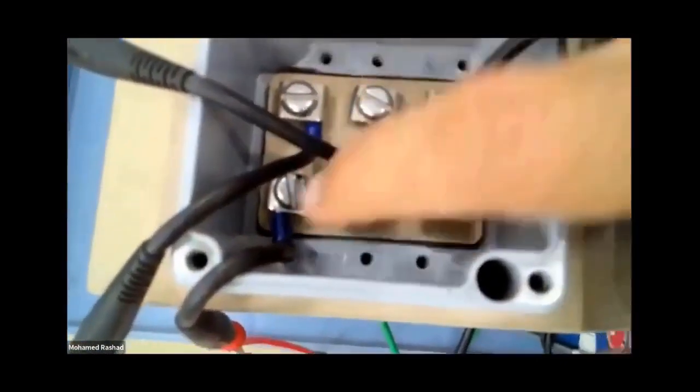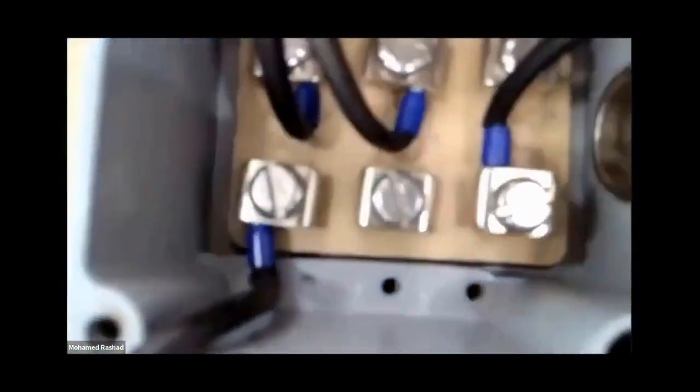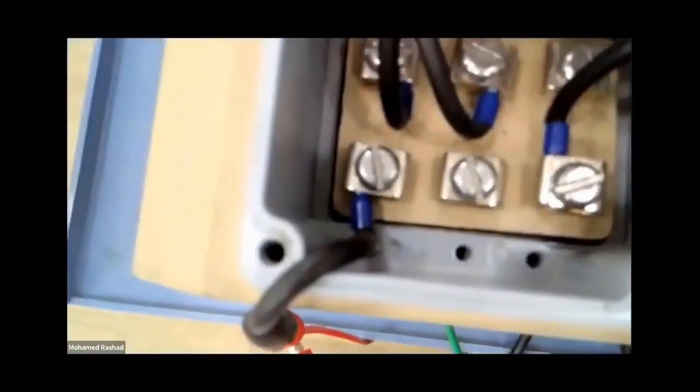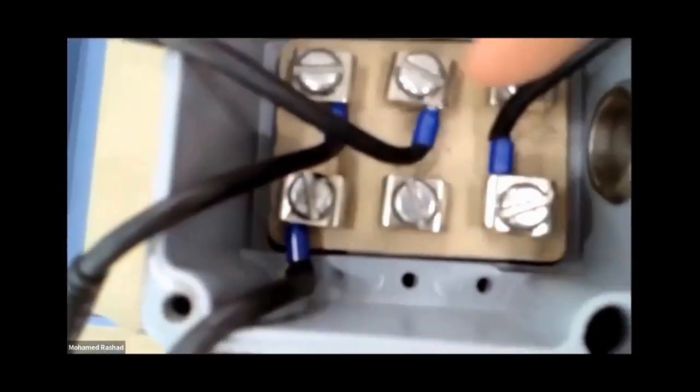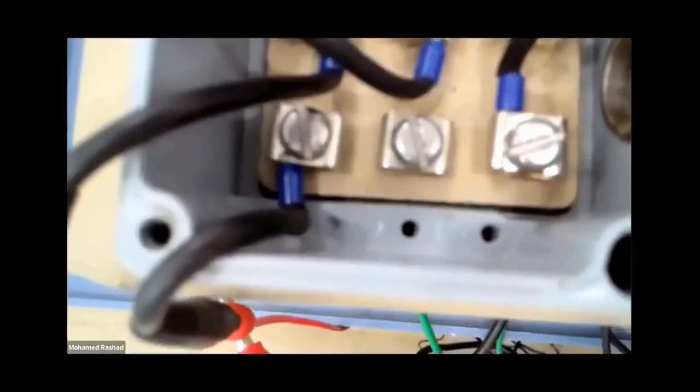This terminal is labeled here, inside like this. If you look here, it is labeled 1S1, 1S2, 1S3, then the one above is the spare, 2S1, 2S2, 2S3. So 1S1, 1S2, 1S3 belong to the first core, and 2S1, 2S2, 2S3 belong to whom? They belong to the second core. Nice, guys, that's good. Okay, let's go back here again.